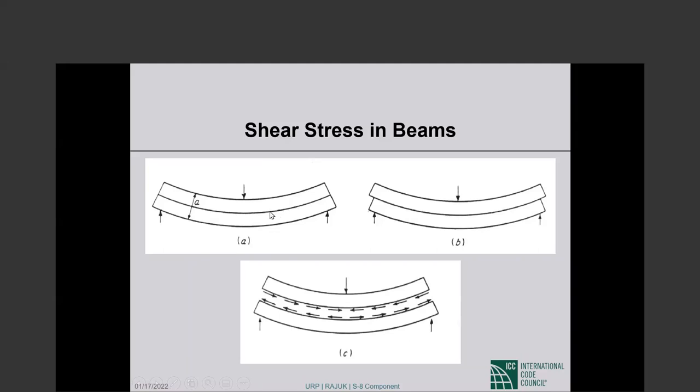If the glue is strong, then the beam bends like one beam as shown in the first picture. You wouldn't even know that the glue is there. However, if the glue is weak, then there will be slippage of the upper portion with respect to the lower portion along that interface, and the bend configuration of the beam will be as shown in the second picture.